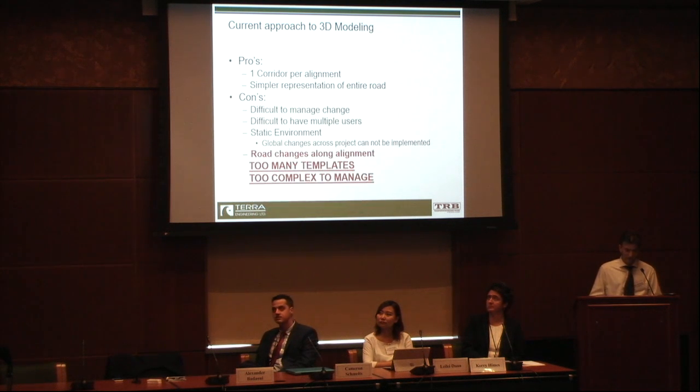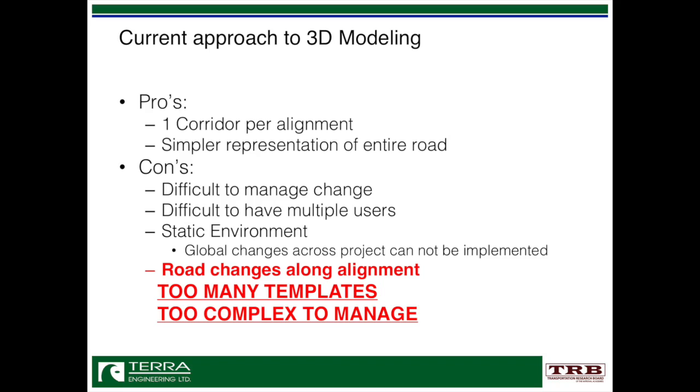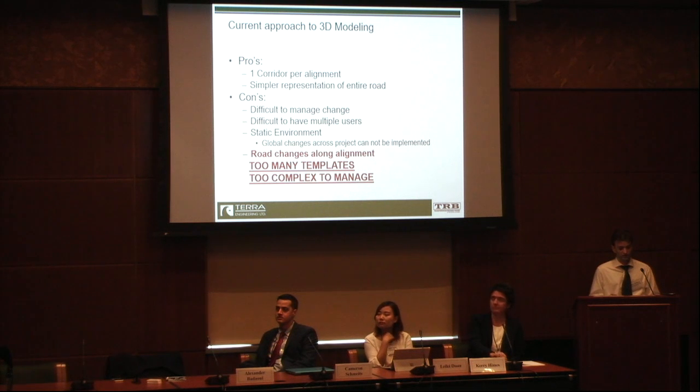However, the cons, that's just a small part of the cons, but the biggest part I want to mention is the stuff in red. The road changes so often along the road that the templates you need to build are so complicated that only the person who made them can edit them and change them, because design builds, especially large projects, change every 10 minutes about what they feel like on the road. So in order to be able to change the products, these templates need to be so comprehensive to cater for every scenario, it's too complicated. And if that person is hit by a bus, that person's sick, that person leaves the company, who's going to amend the template?